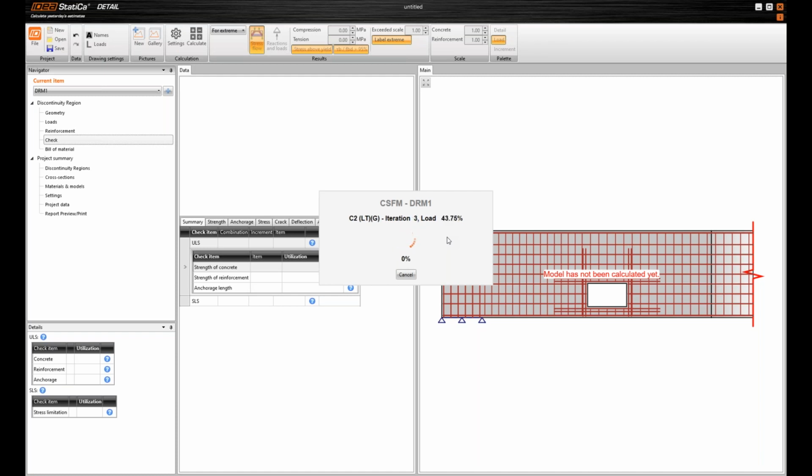And this is a completely nonlinear analysis. So the elements are 2D walls, the reinforcement is real and is connected to the edges of finite elements with a multi-point constraint. Right. So we will soon have the results of the analysis.